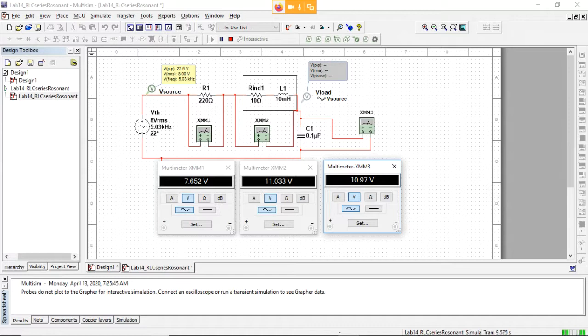And this is the point that we talk about when we talk about resonance. I've talked about it before, but you've got this inductor and this capacitor, and they're basically playing hot potato, passing back the energy. The inductor is storing energy for half of the cycle. During the second half of the cycle, the inductor is dumping its energy, but the capacitor's catching it and storing it up. And so at resonance, we see here that the resistor is dropping effectively the 8 volts.